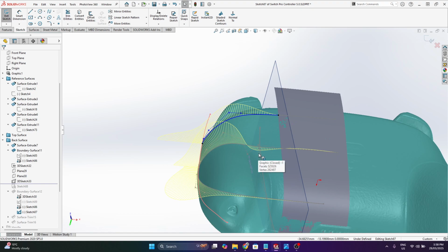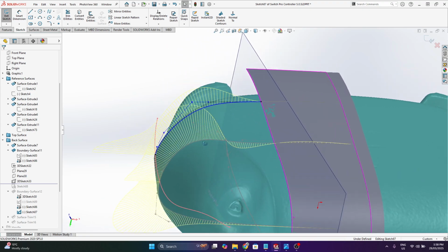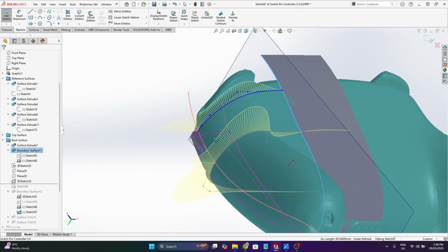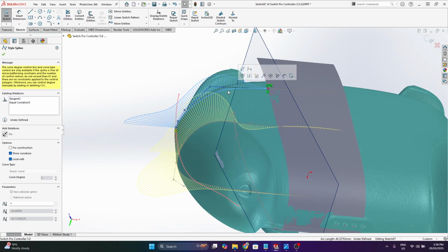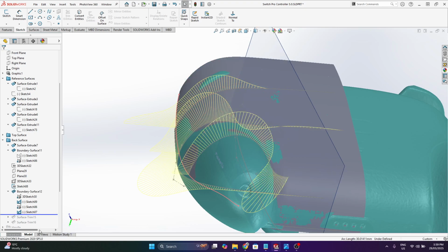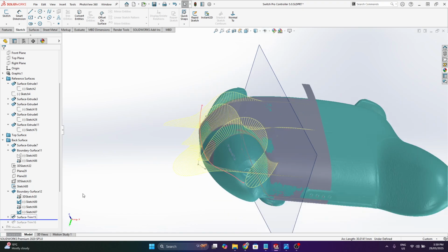If you omit these, you just don't necessarily get the intended control you want. You can imagine there are essentially infinite ways you could blend the edge of this surface to this red line. So you need to draw in something to give SolidWorks an idea of what you want. But you also need to make sure that these curves you're drawing in, at least across the flat planes you're drawing them on, have the same kind of curvature at the transition. So I hope that makes sense. Sorry, I'm really realizing there's a lot to unpack maybe for beginners to intermediates.